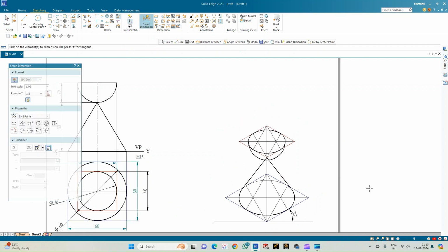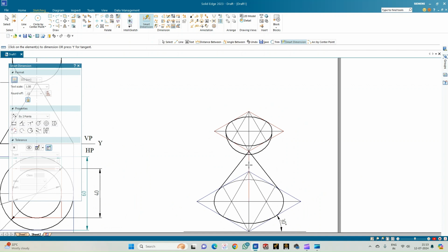So to show the dimensions, you can just see here now it has been reduced. So the actual height in the true scale was 50, but now the ISO scale has been reduced to 40.8, but in the isometric sheet it will be equal to 5 boxes. So you can just unlock this, enter it as 50, and show that it is the ISO dimension. Similarly, we have got the hemisphere here.